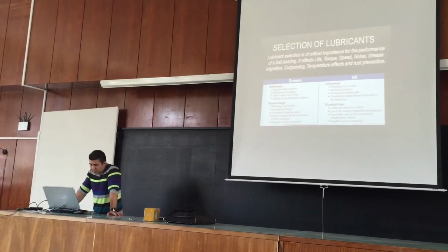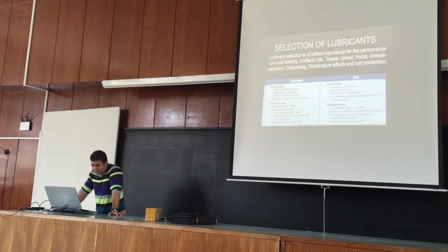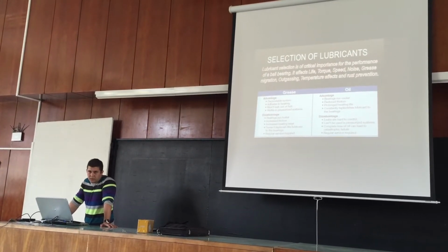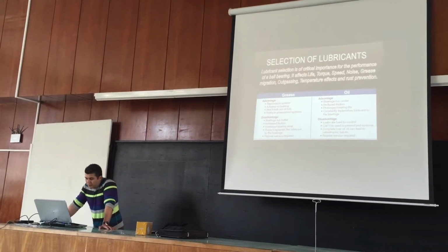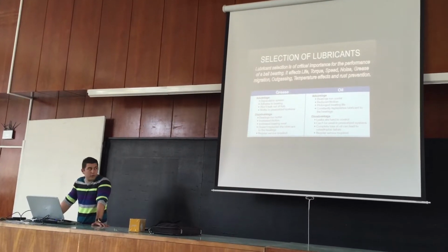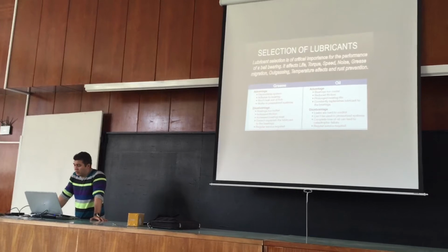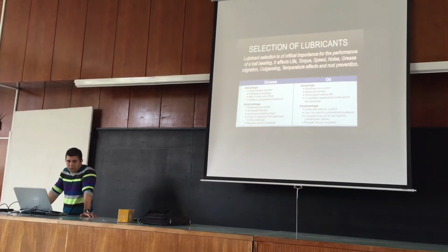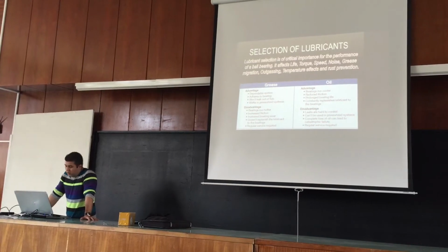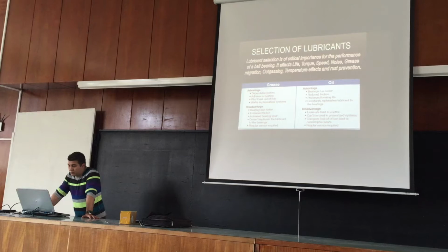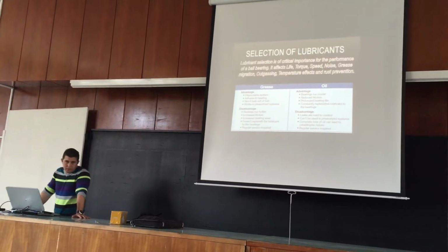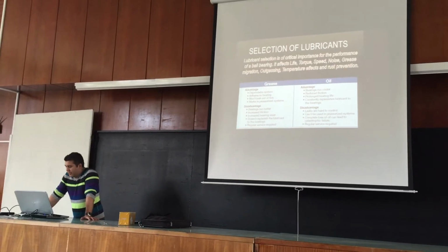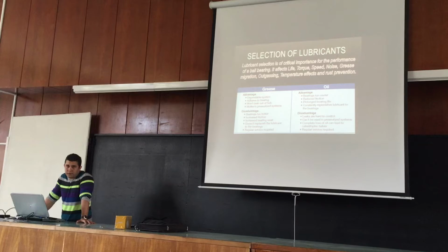And if we talk about disadvantages, for grease, bearings run hotter, increased friction, increased bearing wear, which is the opposite of oil bearings, those three, and it doesn't replenish lubricant to the bearings, and also requires regular service. And disadvantages of oil: it is hard to control and leaks because it's not thicker like grease, and can't be used in pressurized systems. And complete loss of oil can lead to catastrophic failure. Like, for example, if you leave your car engine without oil, you're going to have a little bit of trouble. And like grease, regular service is also required.